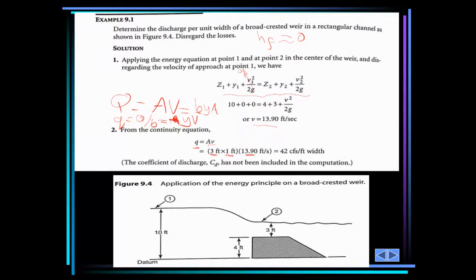And then we look at the water demand. The water demand is also usually in terms of a flow rate, liters per capita per day. So you have the average water draft, the daily water draft, the hourly water draft, and all these are in the form of flow rate. And then you can compare and see: is the flow rate from that stream or river or channel, whatever it is, going to satisfy the water demand?